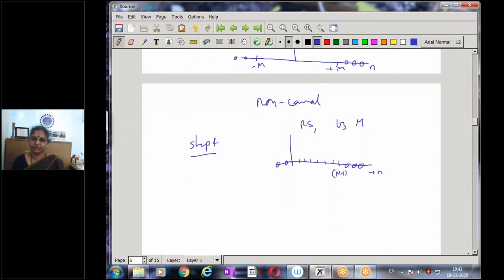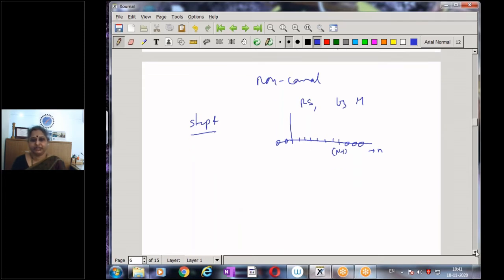So given any H(omega), I evaluate that integral, compute Hn, then I truncate it to some finite duration, and then I shift it to the right by m, and we have a causal response. So this completes our design of the filter.